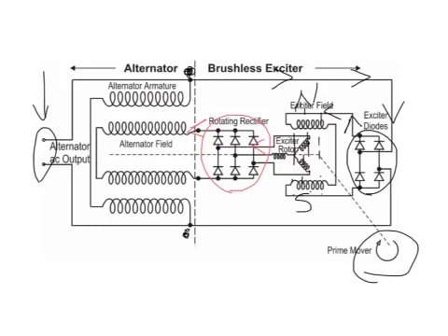Now, unlike the exciter, the alternator field is located on the rotor. So our north and south pole for our field are actually part of the rotor that's turning, which is the opposite to what we had in the exciter, where the exciter field was actually in the stator. Doesn't matter where they are, and as we've discussed in class, the bigger machines, or anything over about 1 kVA or 1,000 volt amps, usually means we have a rotating field in our alternator.